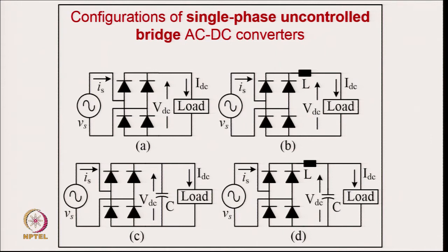Here harmonics are not so high, maybe a maximum of 48% THD, but here the THD goes as high as, in some applications like switch mode power supply, maybe 80 to 90%. Third harmonic is quite dominant, which also causes excessive neutral current, which we discussed in previous cases.